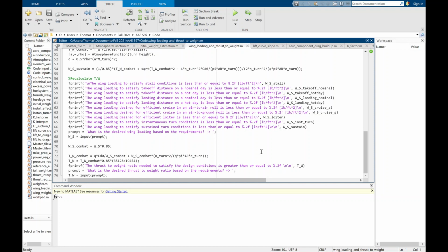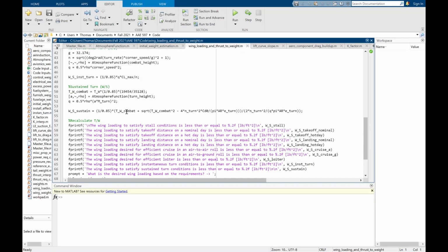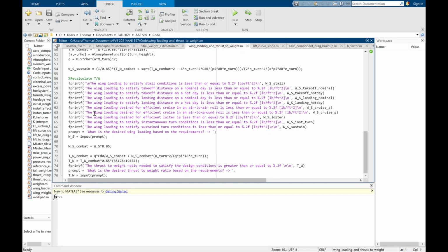So if you were to plot this, there'd be an intersection of the points that would most likely be a minimum, but that might not likely be what you want. If for instance, the wing loading, you wanted a little bit higher to say allow for more cruise or more efficient cruise, or if you wanted the thrust to weight to be higher, you can always have that. Just a larger engine might not necessarily be optimal, but at this point, it's hard to know. So you have to use more refined methods later to determine the optimal wing loading and thrust to weight.